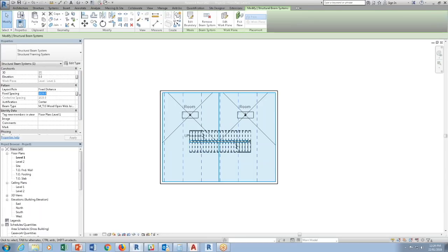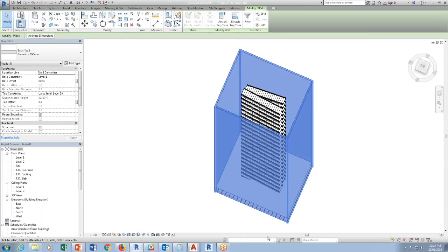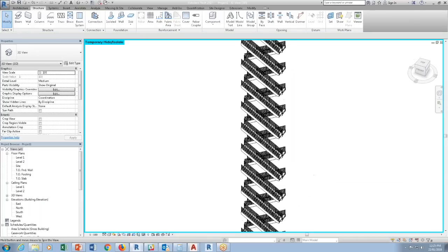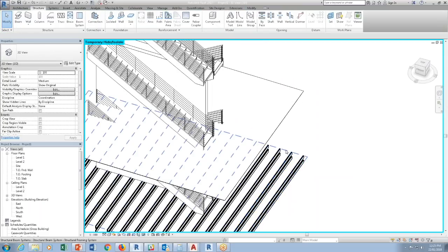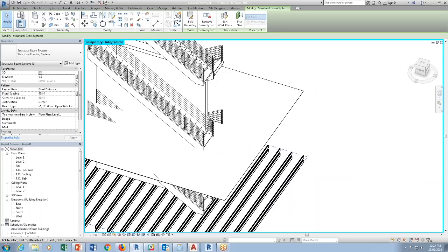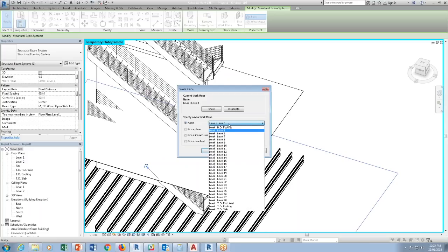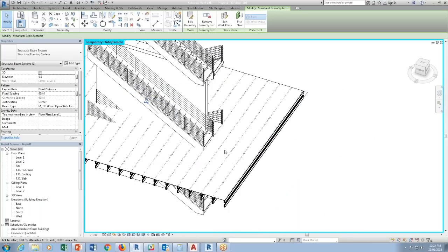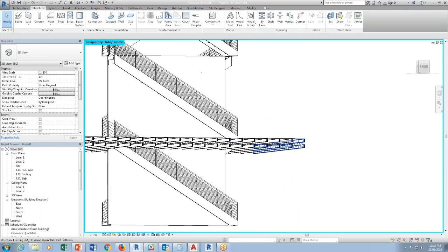So in here, you could go to spacing. Let's say I'm going to go 2 feet spacing. Let me hide this. And you notice that there's your beam right there. Oh, actually I'm putting in the wrong level. You can always change that. Oh, actually I can't. Edit work plane. Ah, I could cheat. There we go. So that's how you do it.